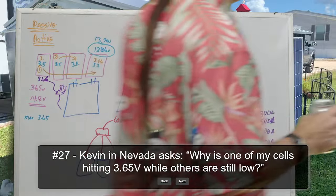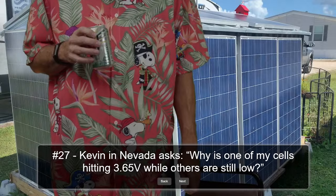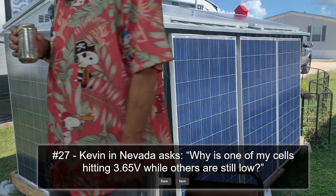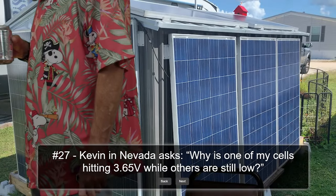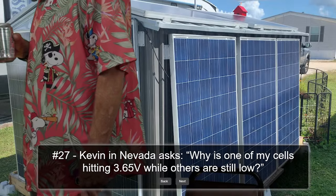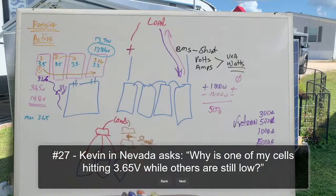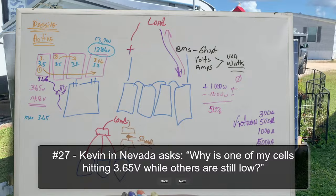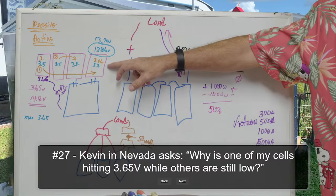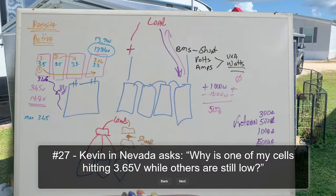Now, the original question was, why is one of my cells hitting 3.65 while the others are still low? And this would be directly related to, your cells should all have the same amount of voltage, and they should all be the same voltage, or as close to the same voltage. And so balancing is required once you get to be 10 millivolts or 20 millivolts out of balance.